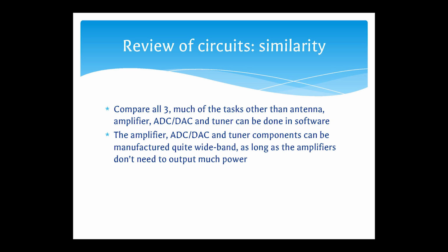And because the amplifier, the analog to digital or digital to analog converters, and the tuners, those are devices that are easier to manufacture pretty wideband. Due to that, it gives you an opportunity to create a system that can emulate or be extremely compatible across a variety of wireless frequencies and modulations. So that gets us to software defined radio.